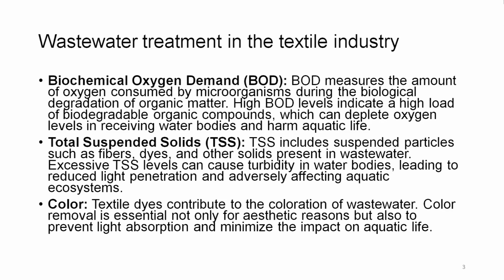Total suspended solids, TSS. TSS includes suspended particles such as fibers, dyes and other solids present in the wastewater. Excessive TSS levels can cause turbidity in water bodies, leading to reduced light penetration and adversely affecting aquatic ecosystem. And this we have talked in detail quite a few times.